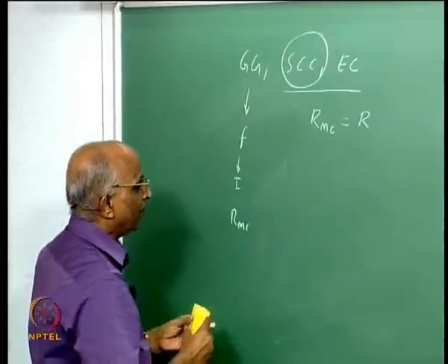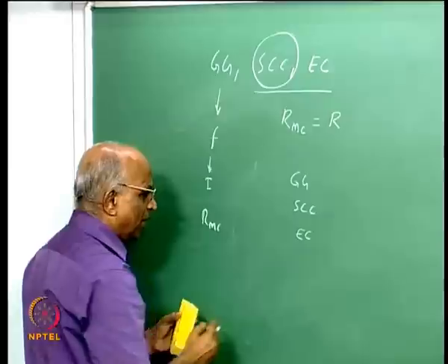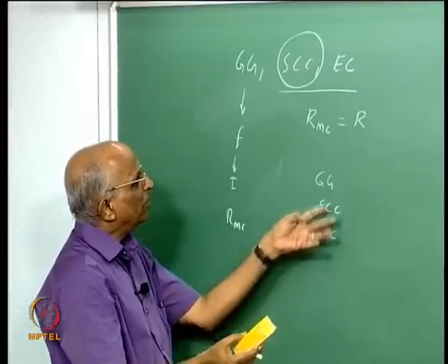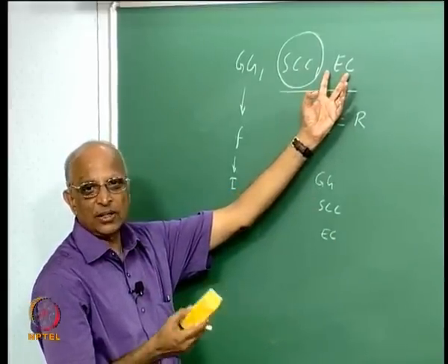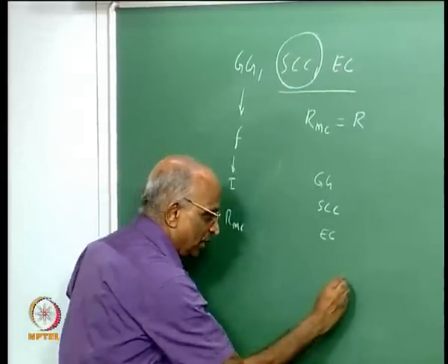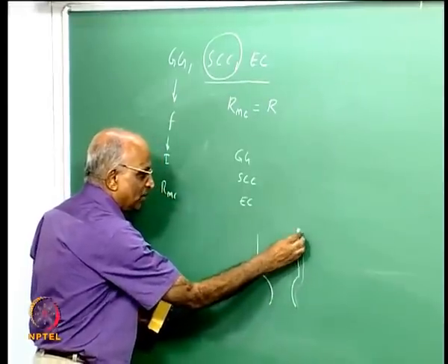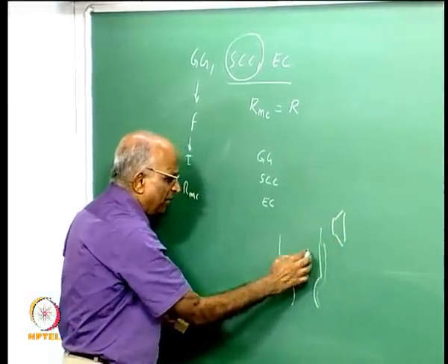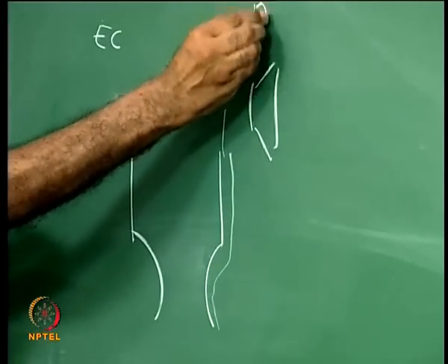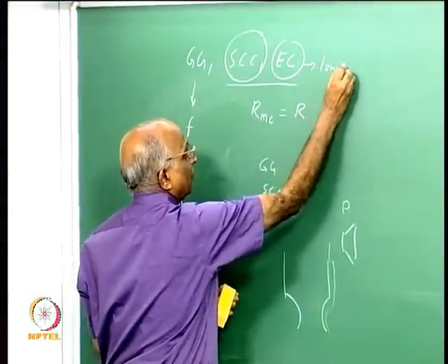I think this is all about the gas generator cycles and the staged combustion cycles, and in the expander cycle we cannot operate at high pressure because we use only a vapor which is generated by heating of the chamber, but this also has some powerful implications. Maybe we will take a look at some examples. Why can we not operate at high pressure in an expander cycle? We are using a chamber which runs hot to be able to form vapor from the propellant, and this vapor is used to drive the turbine. I have a limited amount of heat transfer in a chamber, and therefore I cannot have very high power, and since I cannot have very high power, the expander cycle also operates at low chamber pressures.